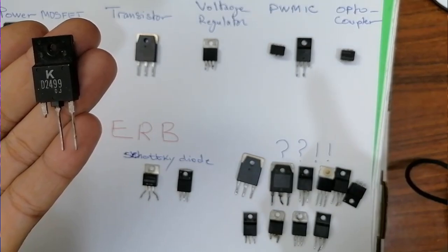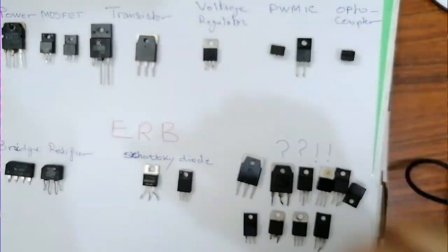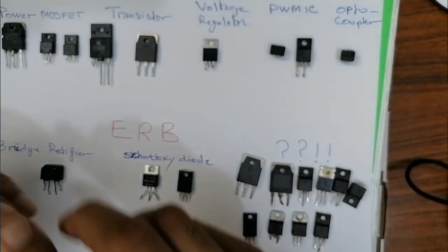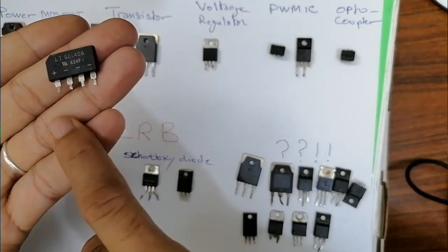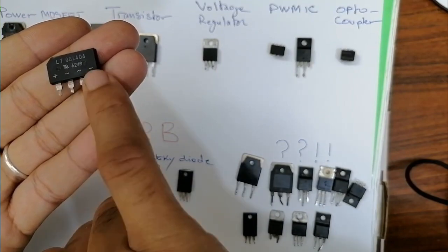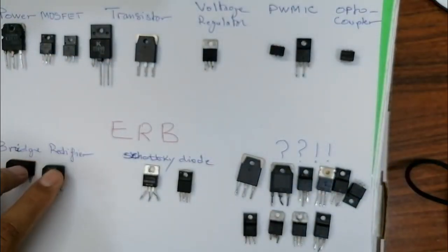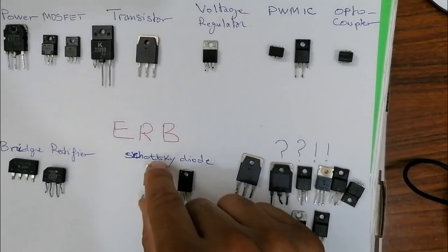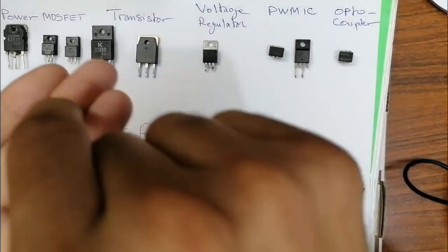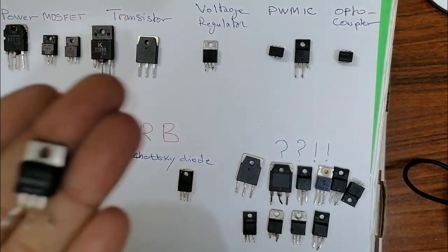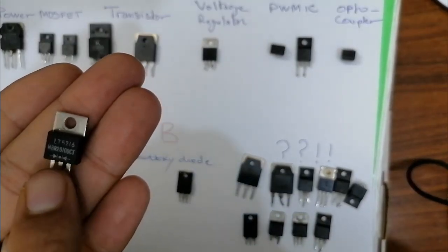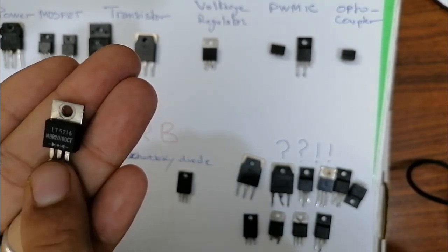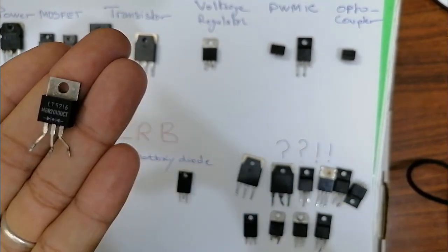Okay? So, based on reference, for example, this type of component, as you can see over here, is a bridge rectifier, because here we have plus, minus, and we have the AC symbol here. So this is simple. This is a bridge rectifier. Okay? And another component like this, where you find 2 diodes connected together, like this one. So this is a Schottky diode or a rectifier symbol.